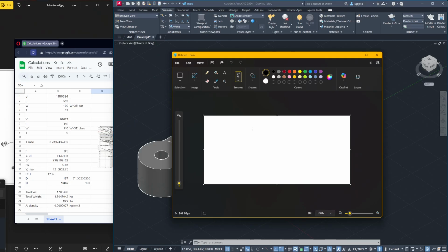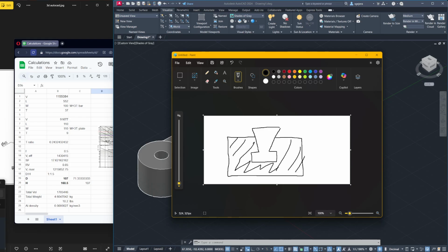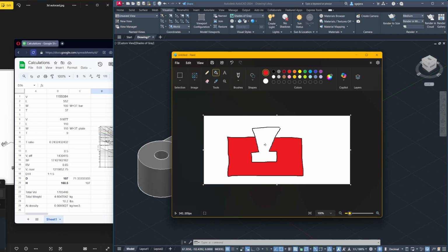So, for example, if this is your object, kunwari, ito yung object, no? So, there is an undercut. Tapos, ito yung molding material mo. So, this is your pattern. Tapos, let's say, ang molding material mo is sand, no? So, this is all sand na to. Pwede sigurong i-paint bucket. Yan, puro sand to. Ito yung pattern mo. So, how can you remove this pattern? Paano mo ma-remove itong pattern na to without breaking the sand? Di ba? Imposible siya kasi may undercut ka dyan.